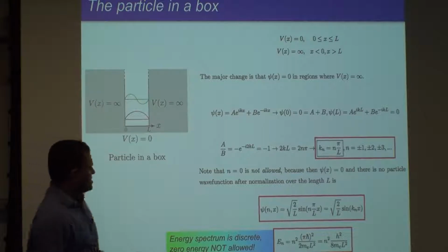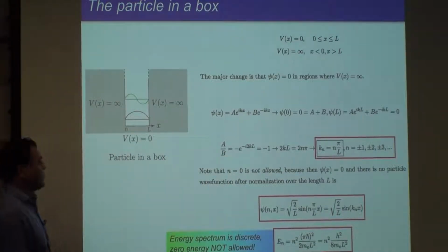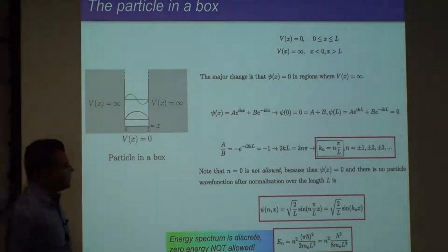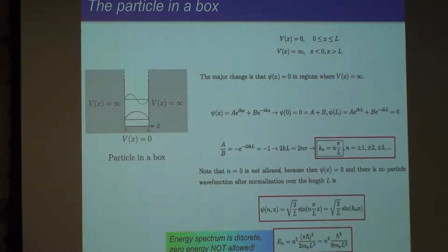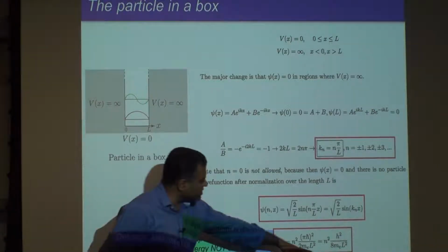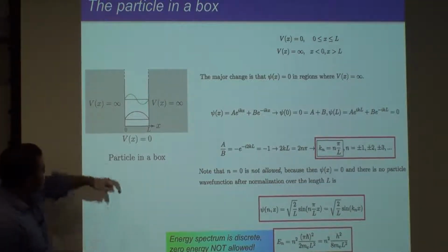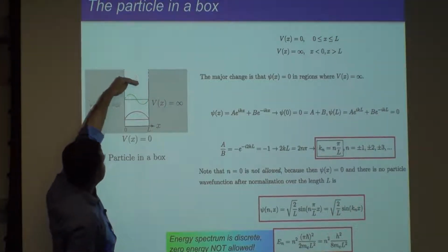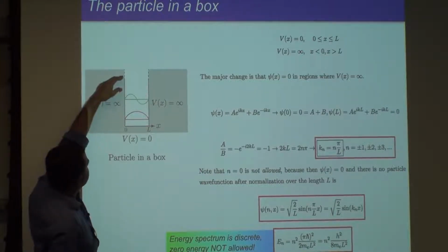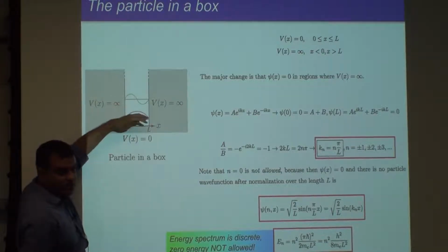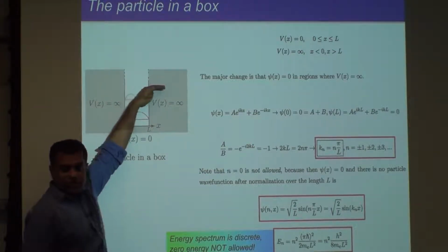Right? And this is a very important parameter, the square of the well width. We'll see today that for the highest mobilities of electrons in quantum wells, which are used for high-speed transistors, this is a severe restriction. If you want to make a very small transistor, you want to make the length smaller and smaller. But as you do, these energies start floating up, and in all physical devices your barrier height is not infinite, it's finite. So you have a limitation as to how small you can make one.